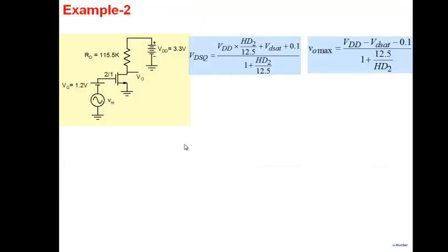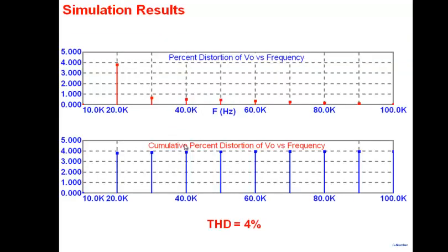Okay. Let's take another example. Let's see, what am I doing here? Yes. According to theory, we should have had only second order harmonic distortion. But this is because we are using the BSIM3 model rather than a square law model. So it's not a square law only.